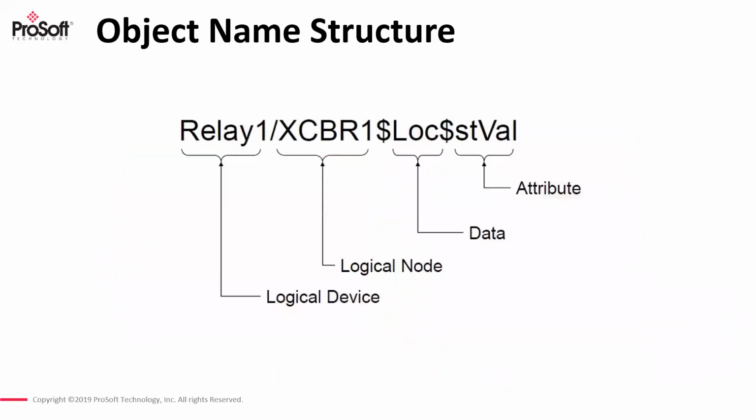And with IEC 61850, what they did was take advantage of an object name structure in this data model approach, where they broke things into logical devices, logical nodes, data, and data attributes. And so throughout this structure, it provided a very descriptive tag name that could be used on the device side, as well as on the substation automation side.